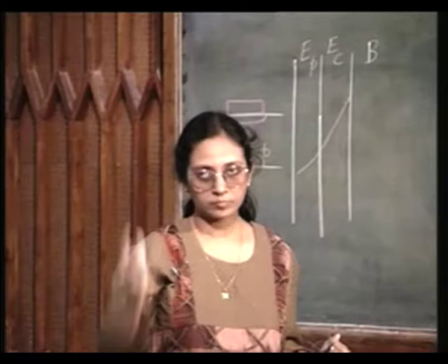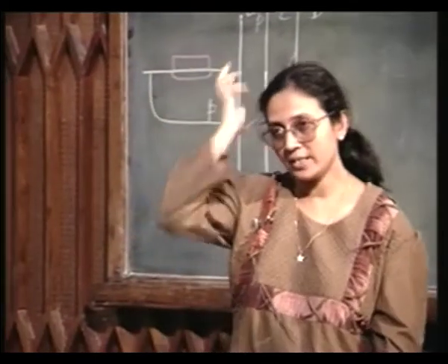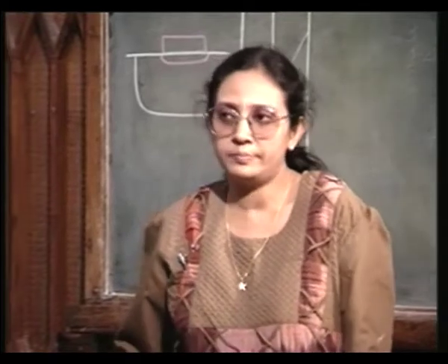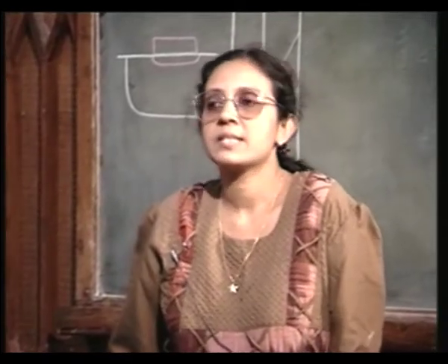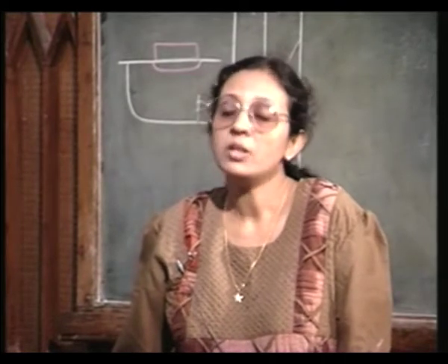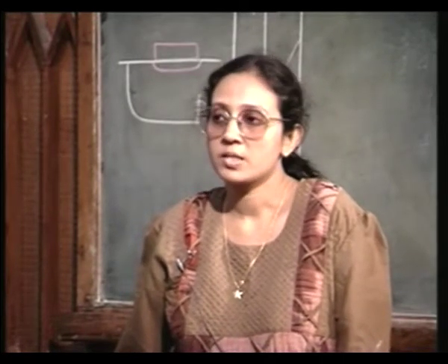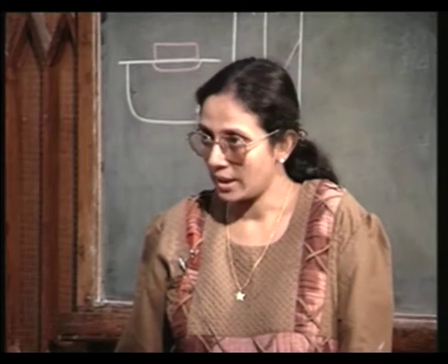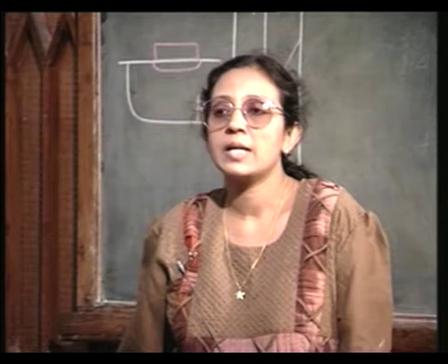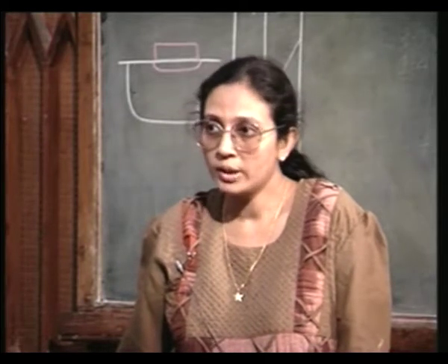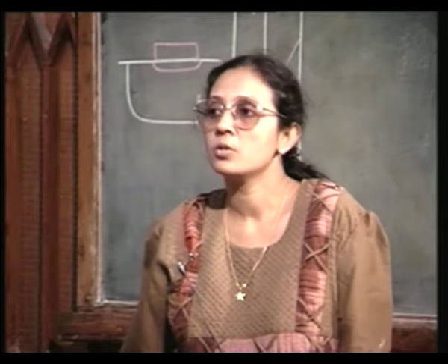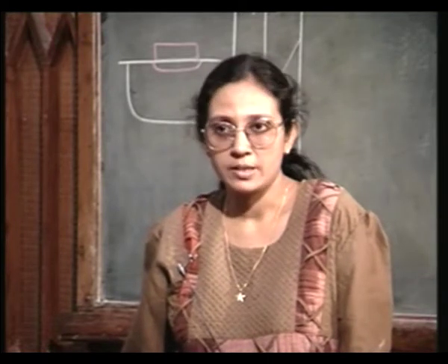Now, we have underlined the basic strategy. What are our requirements? First of all, the extrinsic base must be self aligned to the emitter, and the other thing is that in order to realize a shallow emitter without having to sacrifice the gain of the transistor, we must use a poly emitter.